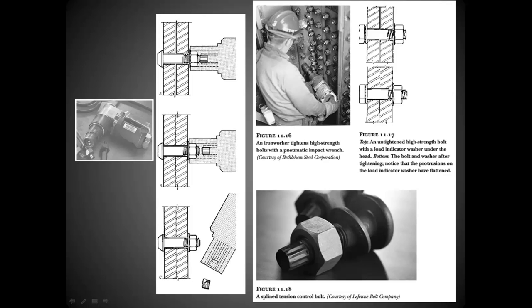This allows you to very quickly and easily put a lot of bolts in place, and you are assured that they are tightened to the proper tension or torque in the steel. In the construction process, we have people that go out to the steel framing and check the bolt connections to make sure they are tightened properly, and they'll do that within certain areas. They'll pick and choose which ones they test, and really give you a second look to make sure everything is tightened down to specifications.